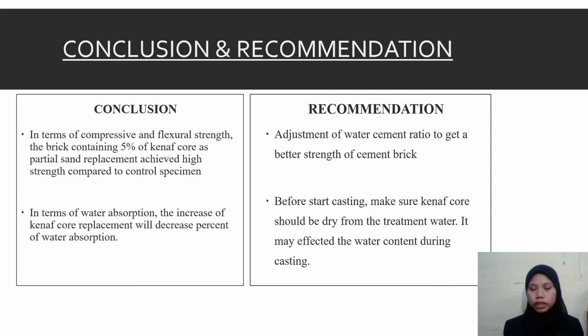The first thing to do is to adjust the water cement ratio to get better strength of the cement brick. And before starting casting, make sure the Kenaf core is dry from the treatment water. It may affect the water content during the casting if we do not dry the Kenaf core first.